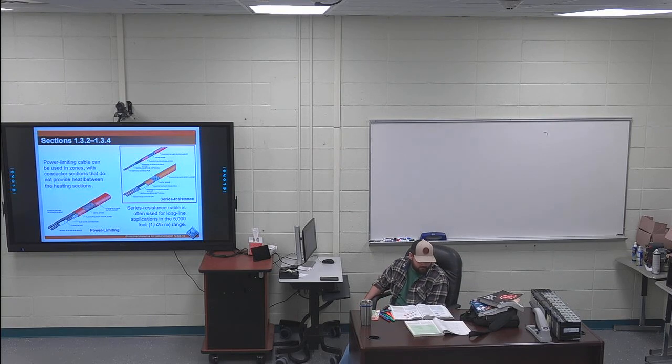134 long line cable installations, page 6. First paragraph, second sentence through the end of the paragraph is highlighted. Some applications may involve cable lengths ranging between 1,250 and 5,000 feet that are powered from a single source. For many of these long line applications, specifically designed self-regulating and mineral insulated cable systems are used. So if you need a long run of this heat tracing, you're only going to use the self-regulating and the mineral insulated cables.